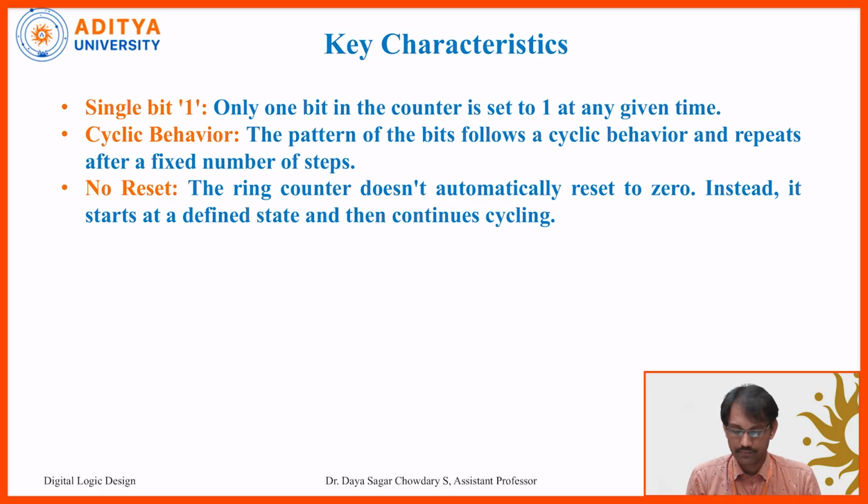Now coming to the key characteristics. Single bit: only 1 bit in the counter is set to 1 at a given time. Cyclic behavior: the pattern of the bits follows a cyclic behavior and repeats after a fixed number of steps. And no reset: the ring counter does not automatically reset to 0.